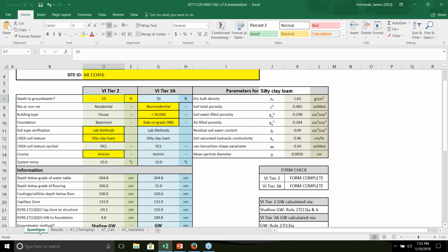Well, the well log says 10 feet, but actually it's 8 or 7. A lot of times we've seen historically well logs that have identified groundwater at 10 feet, and yet when we put in a well, we see it at much shallower depths that could be 8, 7, or even 6 feet. So having a well, if you look online, that's the proper way, and you talk to most geologists, that's the proper way to identify what the depth of groundwater is at your site.